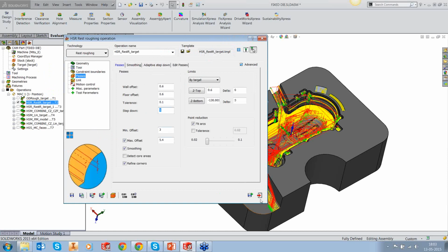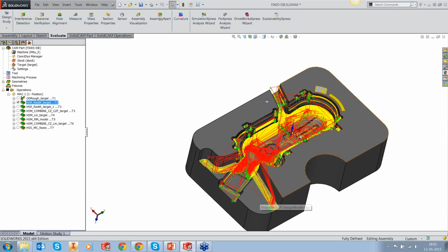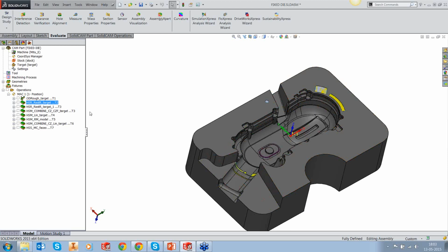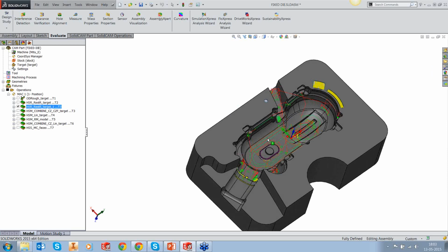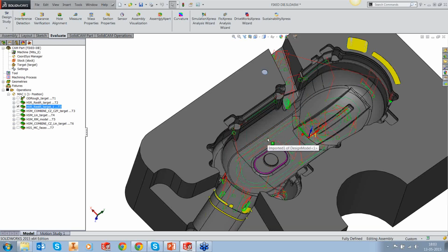Right, so once this has been done, we know that the needed tool length was 65, but it was not enough. So there could be areas where material is still remaining. So we mount another tool, same diameter, but a longer length, about 68 millimeters, reduce our parameters, even the depth of cut and side step, and generate tool paths only on those areas where the earlier tool could not enter. So it's very important to go in stages.